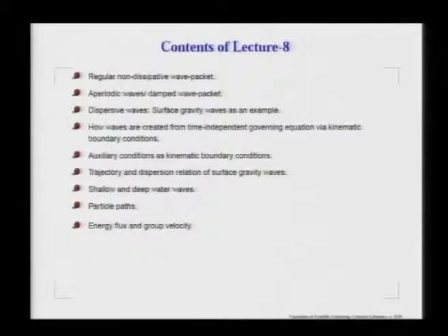And as we said, when it comes to waves, we do not distinguish between hyperbolic or dispersive waves. So, we draw an example of a dispersive wave from surface gravity waves forming over liquids or fluids or water. And what we find is that the creation of the waves does not require the governing equation to be time dependent. That is why we have specifically chosen this problem of surface gravity waves, because the governing equation is Laplace's equation, which is time independent. The space-time dependence of the wave propagation comes about through the boundary condition, and how this boundary condition affects it, that is what we are going to talk about with the help of the kinematic boundary conditions.